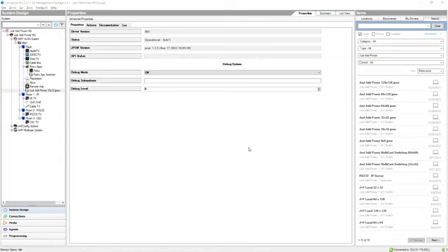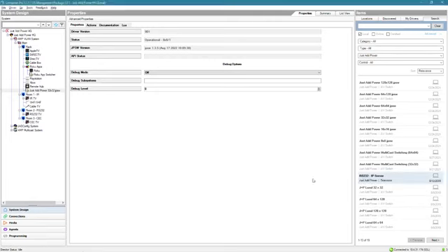And that would mean the Just Add Power device, let's say a receiver, is sending IR commands to a television, or sending RS-232 commands, or sending CEC commands to a television or a source. In that case, you add a RS-232 IP server driver for each television in the system. The second instance that you would add a driver is if you're doing one of our features like video wall or tiling layout control. So we're going to look at each one of those one by one and how to set them up.